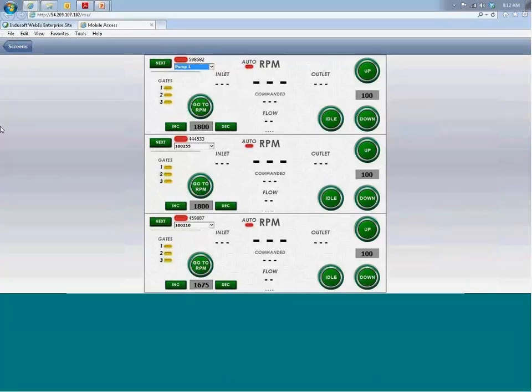So what we came up with is utilizing the InduSoft solution. How do we migrate from a platform that we kind of put together ourselves to something that allowed us to spend the majority of our time on an integration for this customer, and maybe remove those operators because it's not really necessary. It's a manual set of eyes looking at 2 pressure gauges. They're controlling the throttle of an engine up or down, which basically changes the pressures and changes the flow in the circuits. So we went ahead and developed a full control panel and control system locally for each pump unit that's placed out into the field.